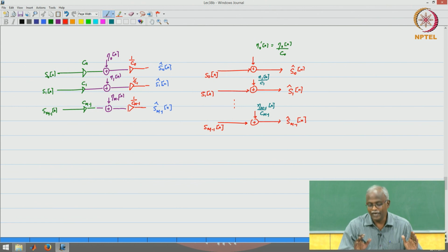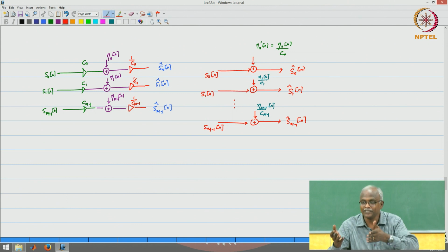And this sort of gives us a very good feel for why OFDM is so popular, because you can now extend this to any number, any m you want. You can say 1024 to 2048, whatever you want, and how many channels you will choose depends on your channel dispersion, and that is something that you can decide. So this is the reason why OFDM has become so popular. There is almost no complexity in this one, because computing the DFT at the transmitter is easy, you can do a fast algorithm, a fast transform, at the receiver another fast transform, and then just some scaling that happens.